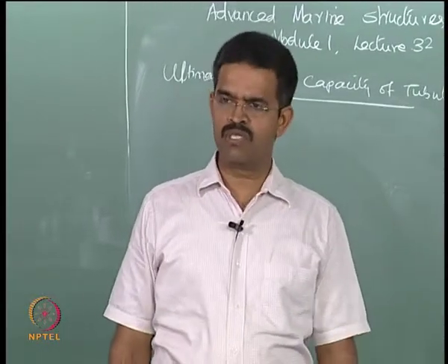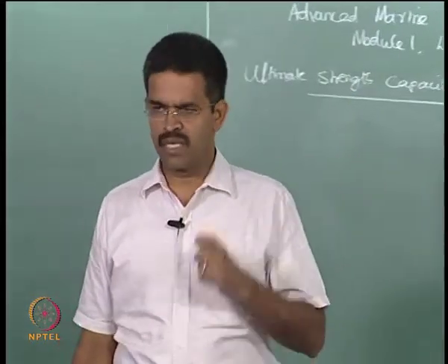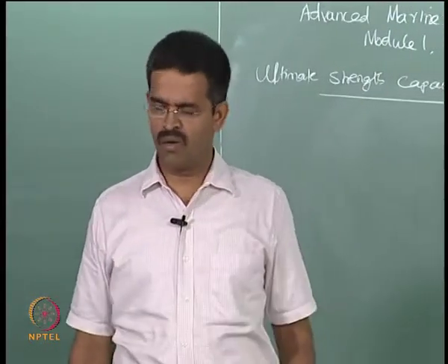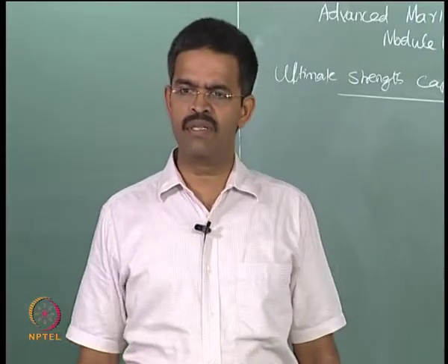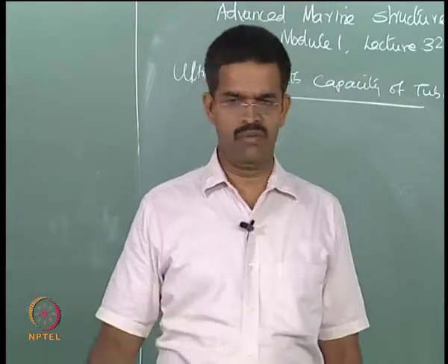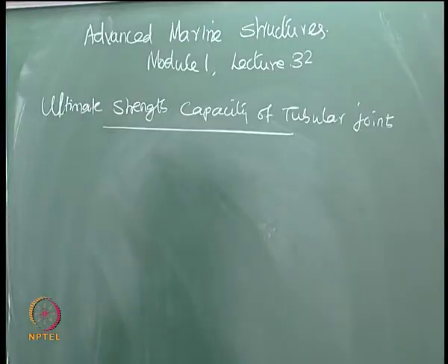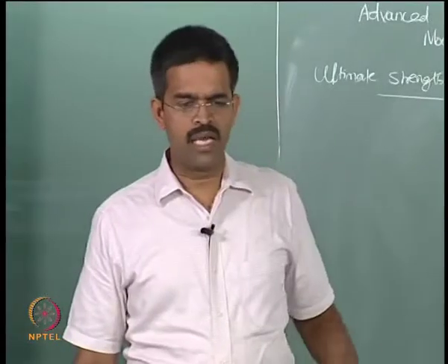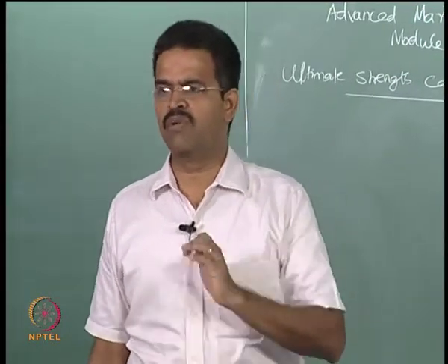So the emphasis was on estimating the capacity by fabricating these joints at 1:1 scale or as scaled models, and estimating the capacity of the joint until its failure. We are talking about the yield value, because in certain cases there have been difficulties with plastic section or plastic hinge formation.